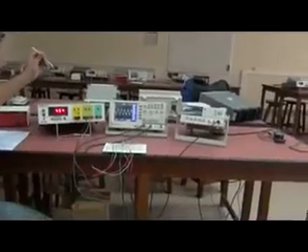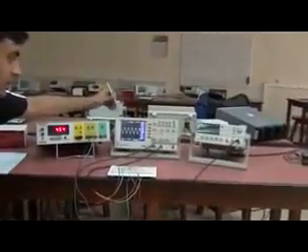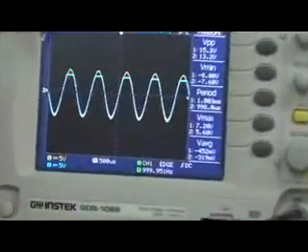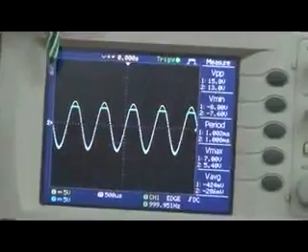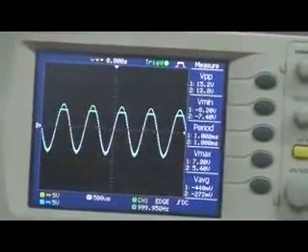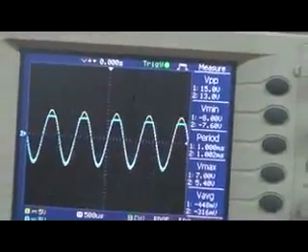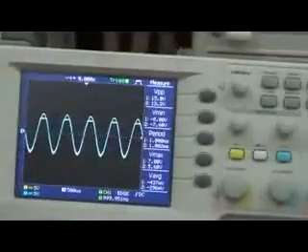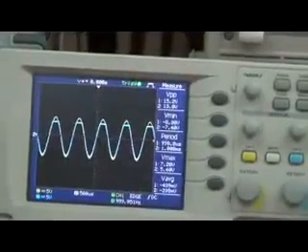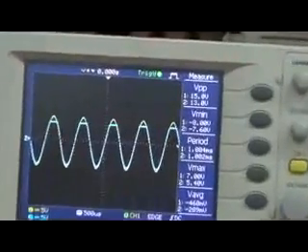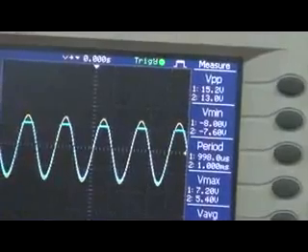For this part, as we can see on the function generator, for the positive part of the signal, there is a clipping that can be seen in this waveform. The yellow one is the input, and the blue one is the output. So we can see a slight clipping for the positive signal for the output. We can vary this clipping through the power supply. Currently we are giving 5 volt plus minus 1 volt to the circuit.